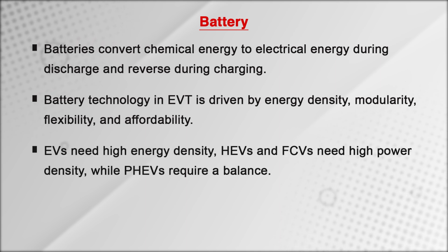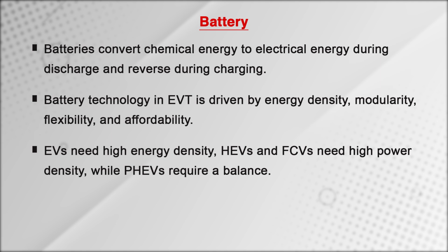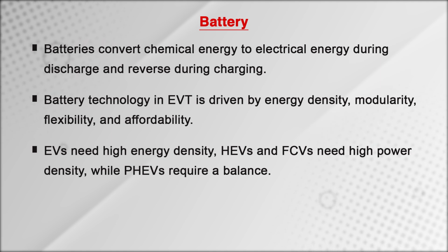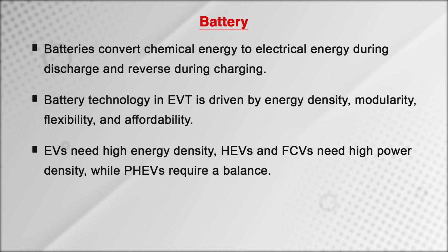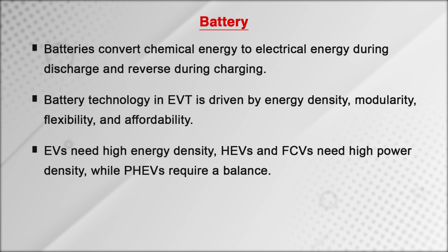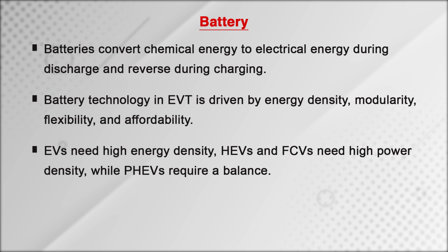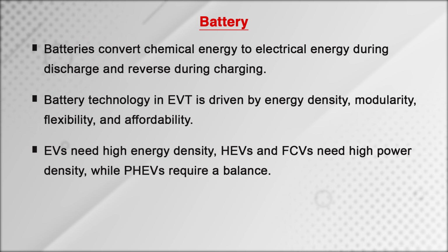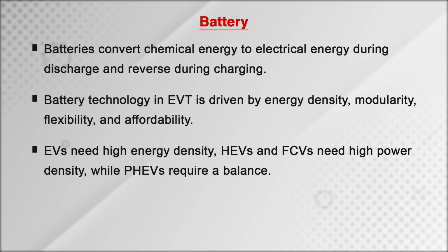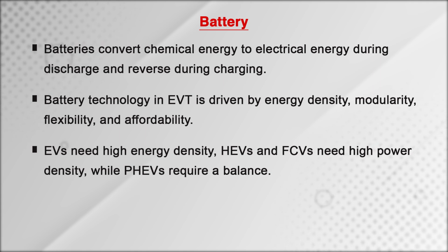The required battery characteristics vary across vehicle types: electric vehicles need high energy density batteries, hybrid electric vehicles and fuel cell vehicles require high power density batteries, while plug-in hybrid electric vehicles demand a balance between energy and power density.